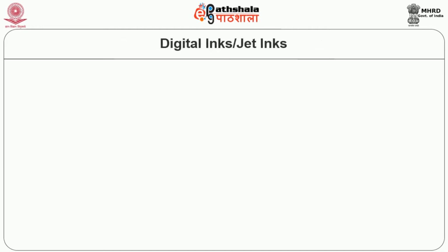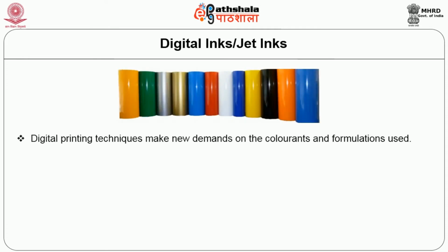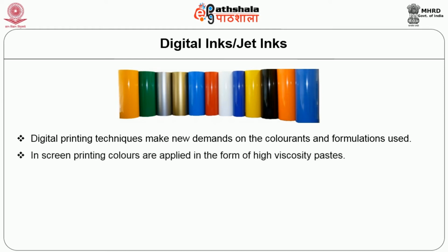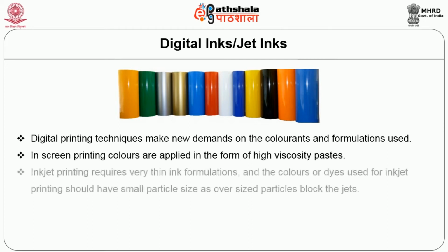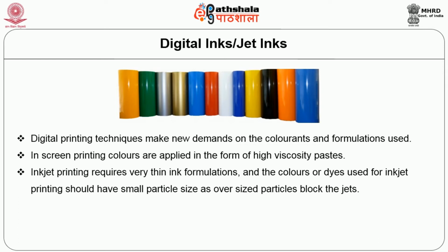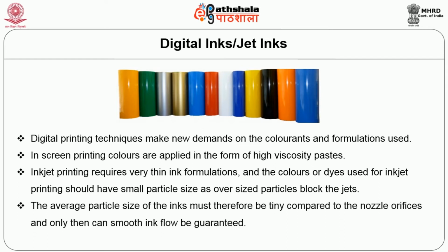Now let's have a look at digital inks, or what are called jet inks. Digital printing techniques make new demands on the colorants and formulations used. In screen printing, colors are applied in the form of high viscosity paste. Inkjet printing requires very thin ink formulations, and the colors or dyes used should have small particle size, as oversized particles will block the jets. The average particle size of the ink must therefore be tiny compared to the nozzle orifices, and only then can smooth ink flow be guaranteed.